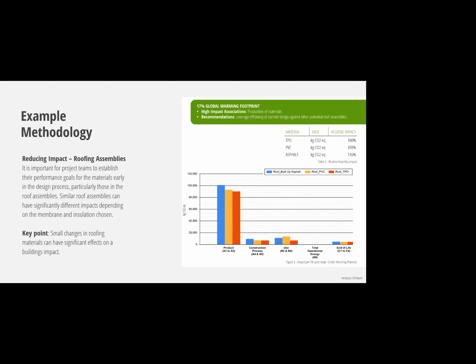But it is a discussion that I've had with envelope commissioners. They don't always like TPO membranes, and that's something where we want to make sure that we're not ever specifying something for a building that's not going to be the best possible material for the performance necessities of that building. So again, it's a balancing act that needs to be hashed out early in the design process so that people understand the pros and cons of the decisions that they're making.